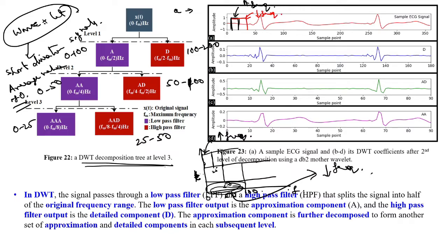Okay. Now since we are changing the scales, this type of three-dimensional matrix what we get, say frequency, time, and the color is the amplitude. So the color matrix what we get, that is regarded as scaleogram. Okay.